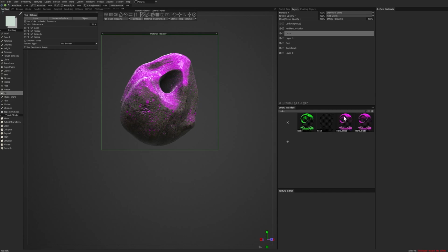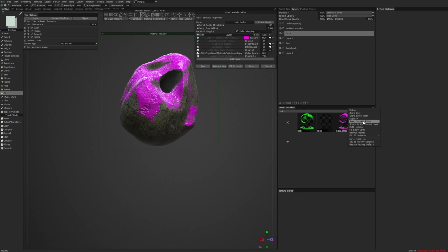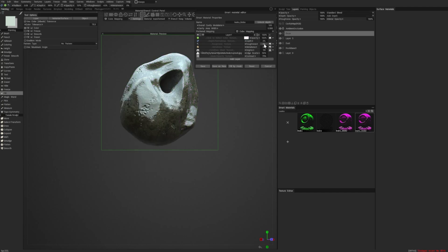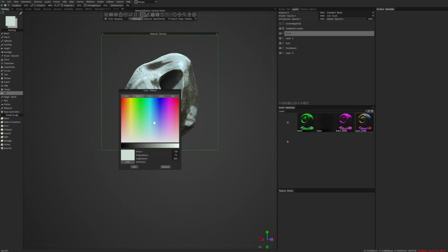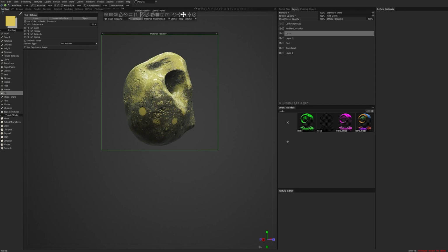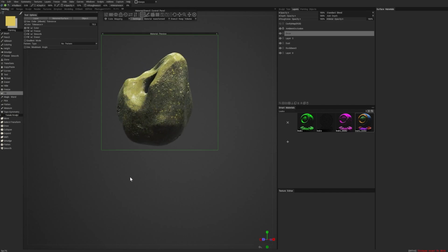Let's right click on this and duplicate this. And on this one, on the duplicate, we're going to go to Smart Material Editor. And again, we'll set this color to white. Okay, and then we'll also set it to modulate. That way I can define the color here. I'll just save that. And now I can choose whatever color I want, and it will use that color instead. Okay, and again, I will just dial up the density on this thing, like so. There we go.